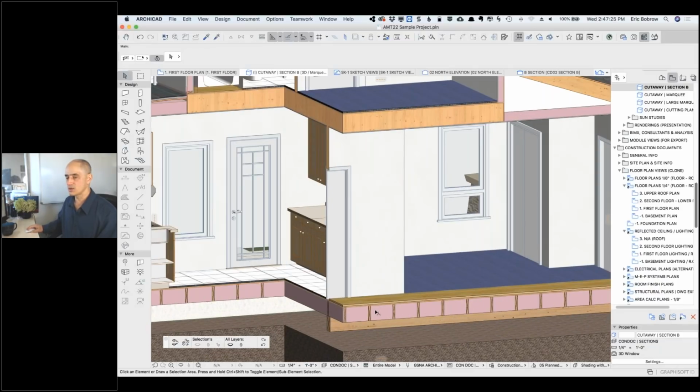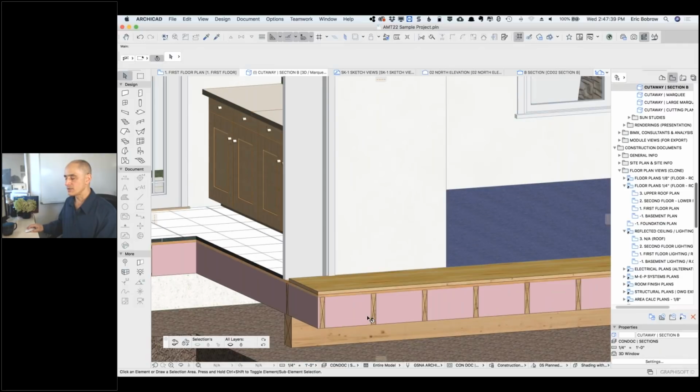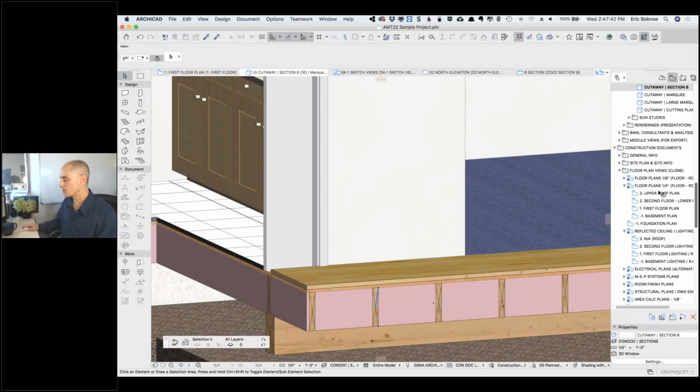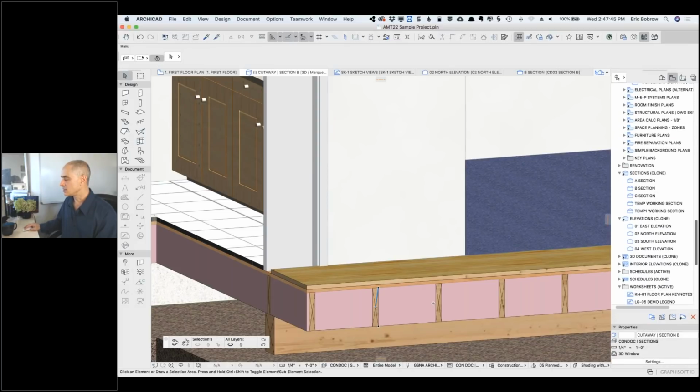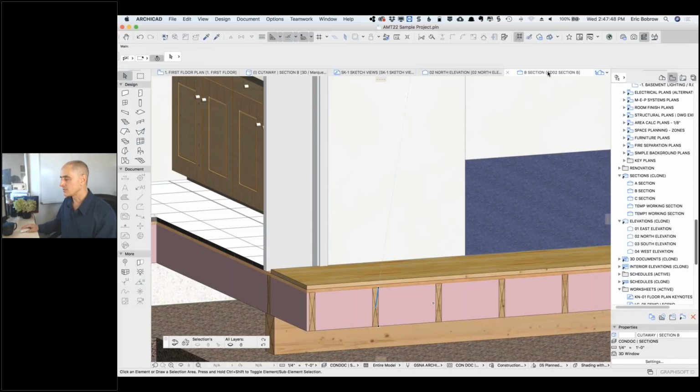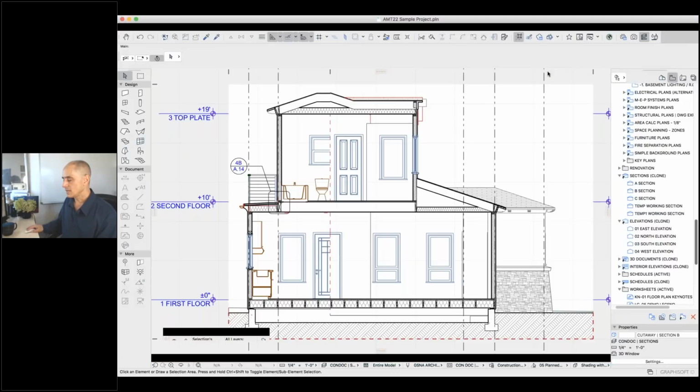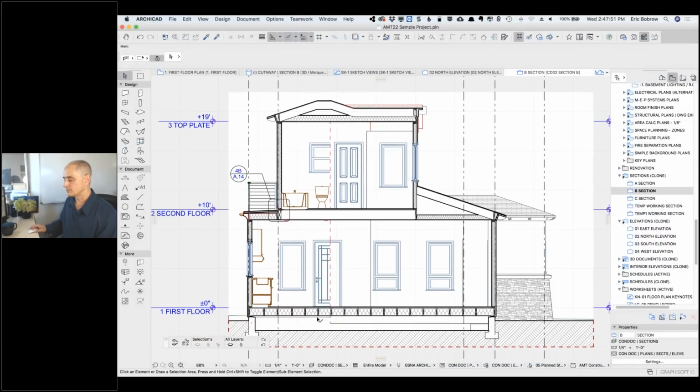So you can see that there's some joists here that are showing up, and if I hover over it, you'll see that it's extending into the building and actually beyond the cutting plane there. If I zoom in on it, you'll see the X that I was mentioning earlier. And let's look at the X here.